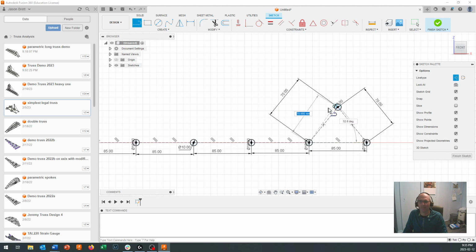And I got a couple of options. One, I can tell it that I want it to come along at the same height as that one and come down right into there. And you'll see that this line has been marked. And if I mouse over it, you see how those two lines blink? They're marked as being parallel to each other. I can come along here and say, well, I want this line and that line to be parallel.